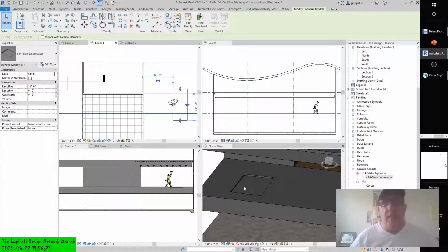All right, so that's the other way. And then you can build it into the assembly of the floor, right? Finally, if the structural requirements allow a thick finish to be applied to a floor without dropping the structural slab, a finished floor element can be modeled directly in place within the structural slab. Actually, that's another way of doing it.